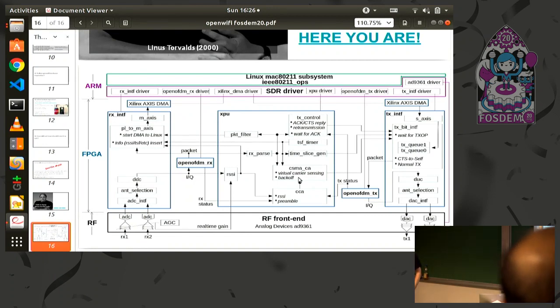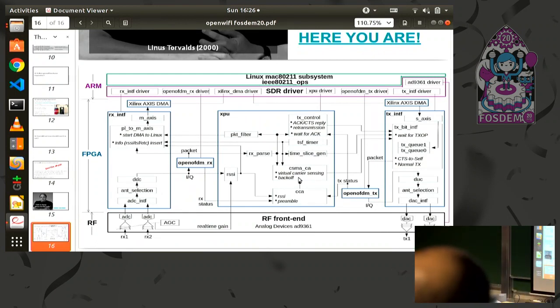Okay. For the TX path, actually there are two queues. Linux asks for at least 4 queues for a chip like this, but currently we implement 2. It still works. So all the packets come from Linux. They cannot go outside immediately, right? First they go into the queue, and the CSMA engine will decide when is the right timing for the next packet to go outside.